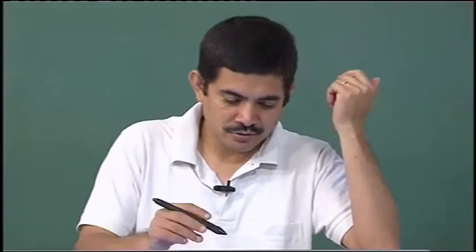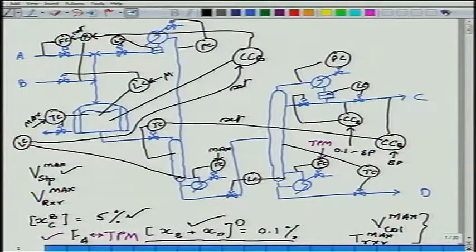When I say everything is set, of course this also has to be max. Operator cannot set, level is set at max, reactor temperature is set at max. Boil up is set at max in the stripper, boil up in the product column is set at max, four things are set at max. Composition is set, composition of the D impurity is set, right. What else is set? I am also maintaining this such that too much C does not get lost. 6 things,